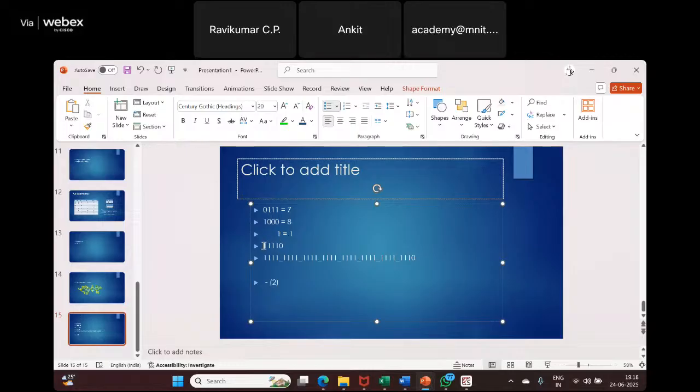When you add two 4-bit numbers, you get a 5-bit number, right? In the same way, when you subtract one 4-bit number from another and a borrow, the result may be in 5 bits. And if there is a borrow, it means it's a negative number.